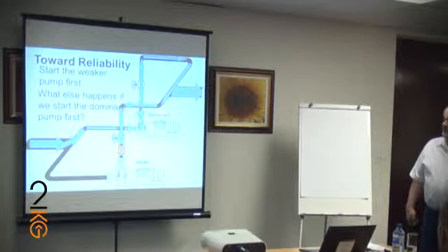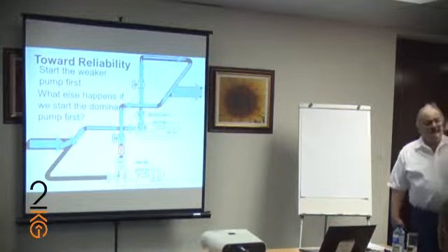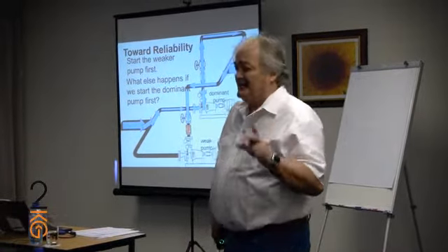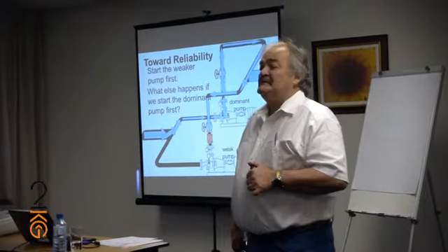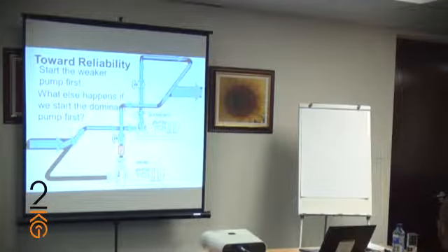So my dominant pump is holding that check valve shut, and this pump is starved on the suction side, and the output is likely to be reduced by the same percentage. So what is the weaker pump really going to contribute to my process? Absolutely nothing.